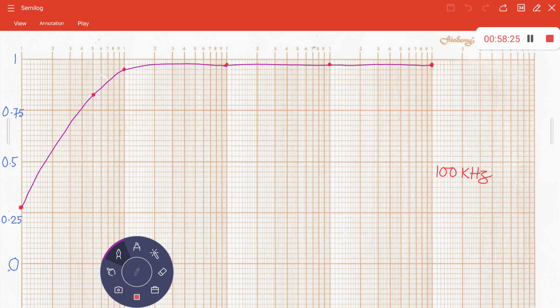Then you have to find out the lower cutoff frequency, that is FL. FL you have to find out for this high pass filter, the lower cutoff frequency. Typically you know that value is given by 1 by 2 pi tau. But that time you did an approximate calculation, and this is the exact calculation. Right? So had this been 0.989,